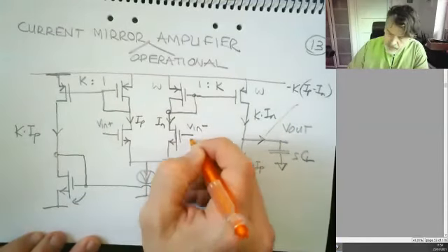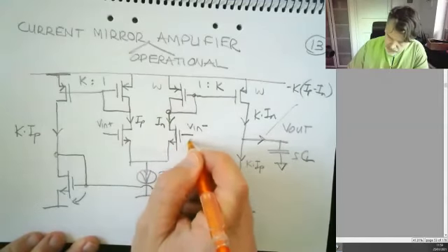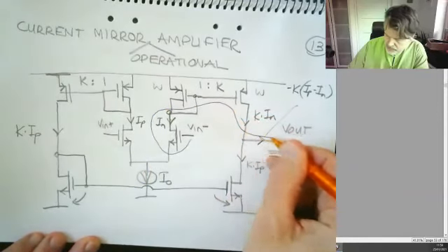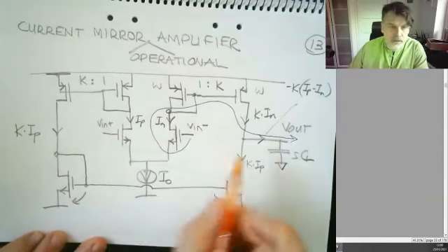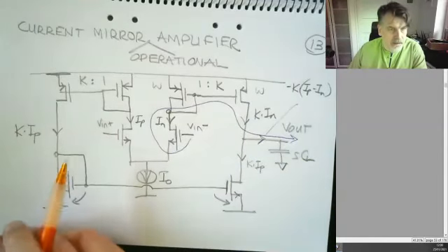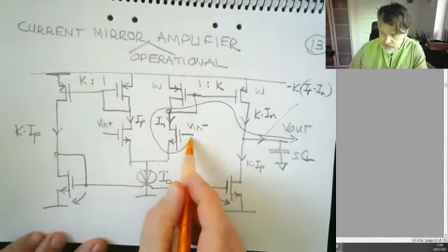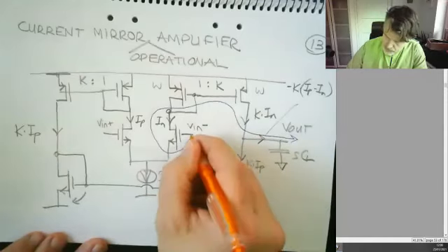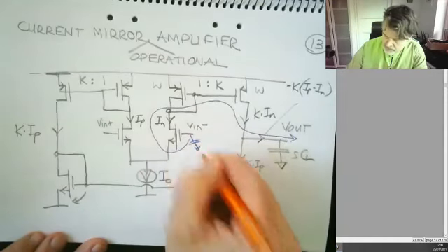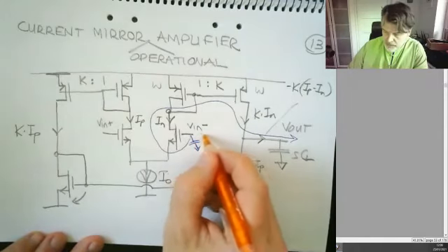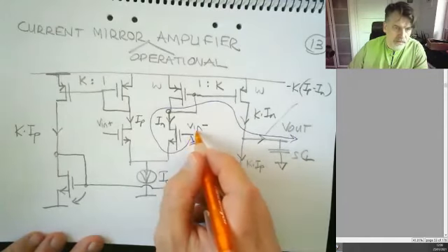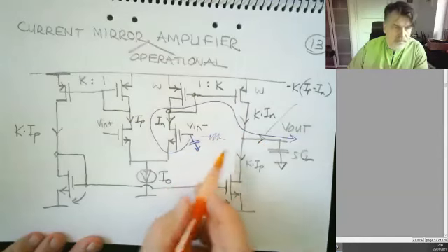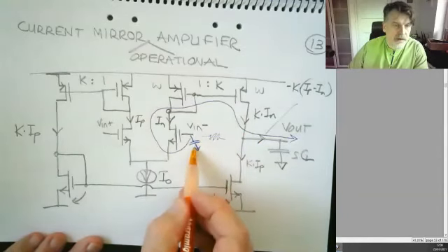So this is my input signal. So I would sort of take, this would be my sort of signal path to the output. And then the trick is to identify what gates I encounter on my path there. So first I encounter this gate, which has a certain capacitance. Oops, you don't see that in your picture. This has a certain capacitance. And dependent on what impedance I have on my driver on the input, I will get the pole here. So dependent if I have some sort of resistance in my driver circuitry, I will get an RC time here.